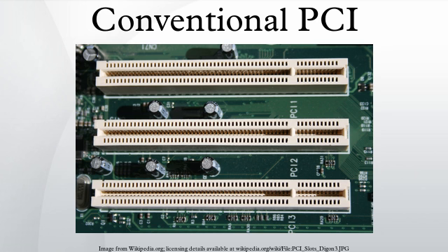MD2 low-profile card: MD2 defines the maximum length of a low-profile PCI card as 167.64 mm and a maximum height of 64.41 mm. Any low-profile PCI card longer than the MD1 length is considered an MD2 card. This is the most common low-profile card form factor. Besides conventional PCI, many PCI Express cards are also described as MD2 low-profile form factor.